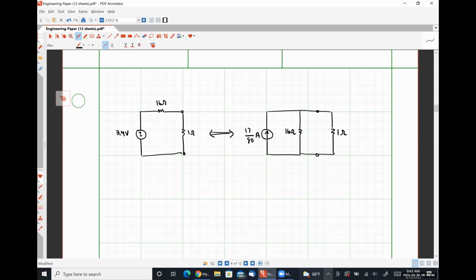On the left, we have our Thevenin equivalent circuit. On the right, we have our Norton equivalent circuit. And since these are both equivalent to our original circuit, they have to be electrically equivalent to each other. Well, as it turns out, it shouldn't be too large of a stretch here. The Norton equivalent circuit is just the source transformation of the Thevenin equivalent and vice versa. And we can verify that very easily, right?